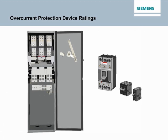Some circuit breakers have what is referred to as a slash voltage rating, such as 120/240 volts. In such cases, the breaker may be applied in a circuit where the nominal voltage between any conductor and ground does not exceed the lower rating, and the nominal voltage between the conductors does not exceed the higher rating.